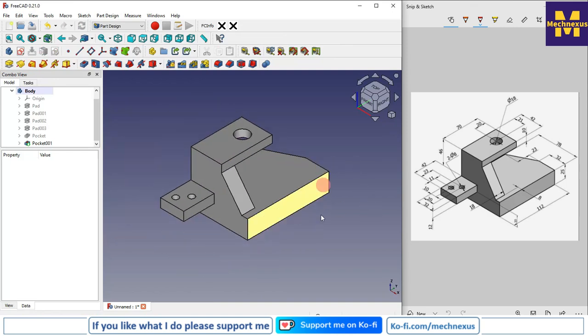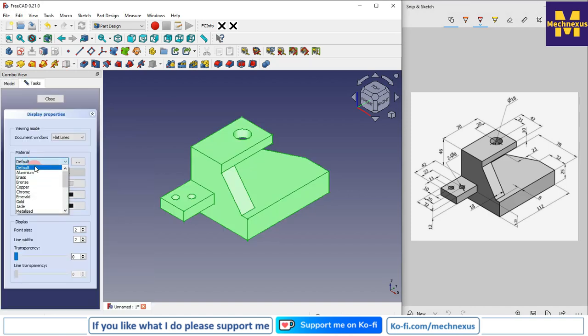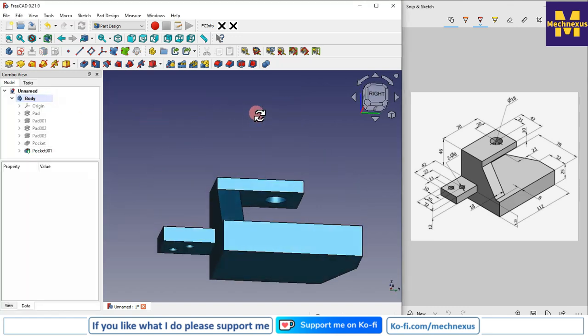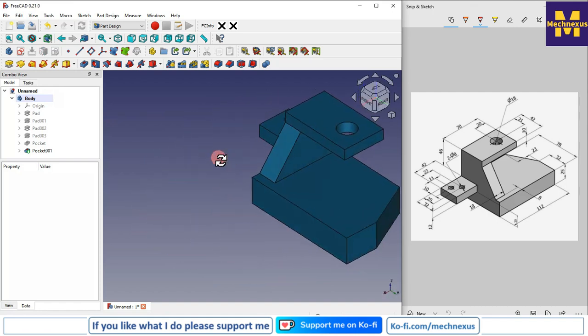So you can see that we have successfully converted this isometric drawing into the 3D model with the help of the Part Design workbench. If you want to apply the material, then go to the appearances and you can select the material from here. Let's say I apply the chrome, and if you want to apply any color to your part, you can select from here, click on close.